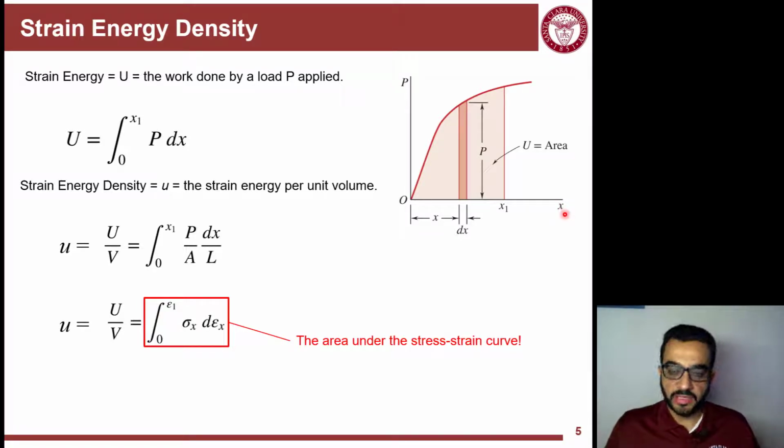So it's related to the stress-strain, but this is the force, not the stress, and this is the deformation, not the strain, because we are calculating the work here. So we're looking for P, the load, and the distance it travels or the deformation it makes. Now another thing we can calculate here is the strain energy density. If you think about density, the regular density we know is the mass divided by the volume. Now strain energy density is the energy or the work divided by the volume. So this is why we call it density here.